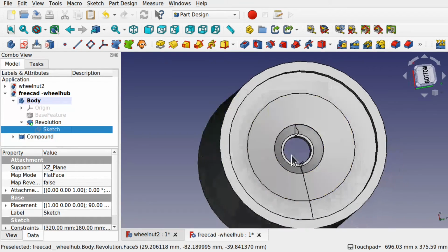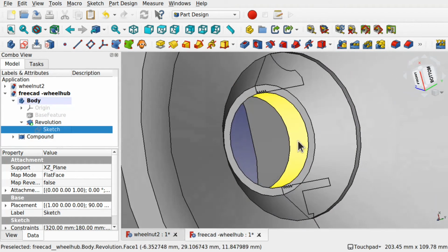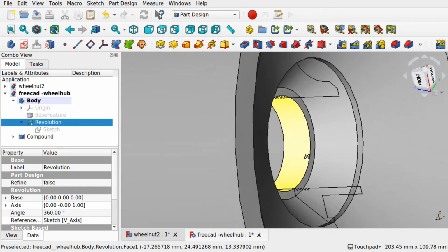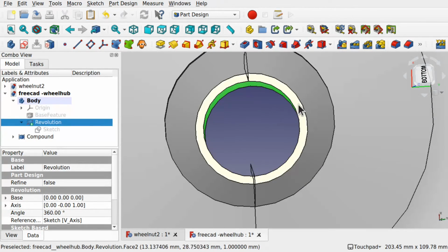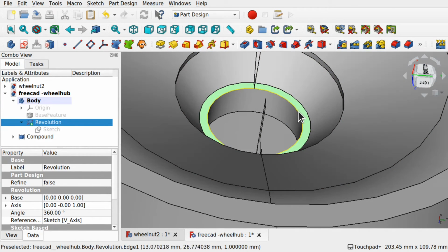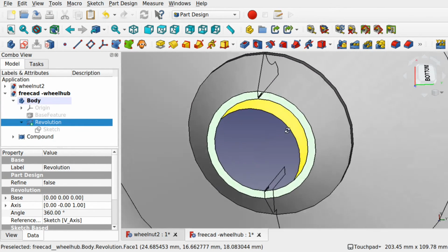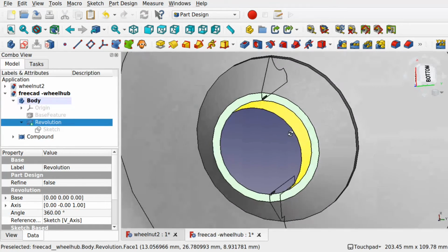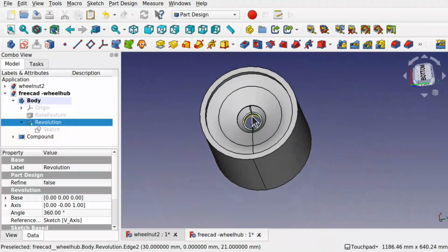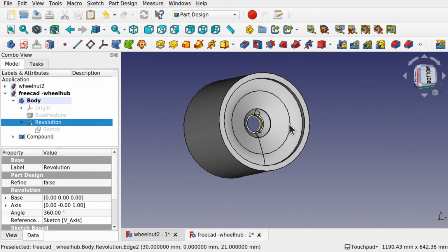Hit close, you can see what's happening in here. So this one is a non-planar face. It's not along one plane. Whereas this one is, create a plane along here. This will sit upon that plane. We can't create a plane for this to sit upon, this one here. So we have to be wary of that when we're creating our revolves.